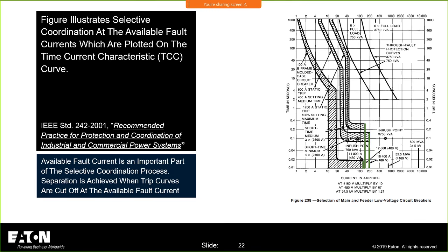I have the portion from a current perspective that it'll just vaporize, but in reality, the trip curve, the damage curve for the thermal damage curve is basically the insulation, because that's the weakest link. So let's talk. I see.